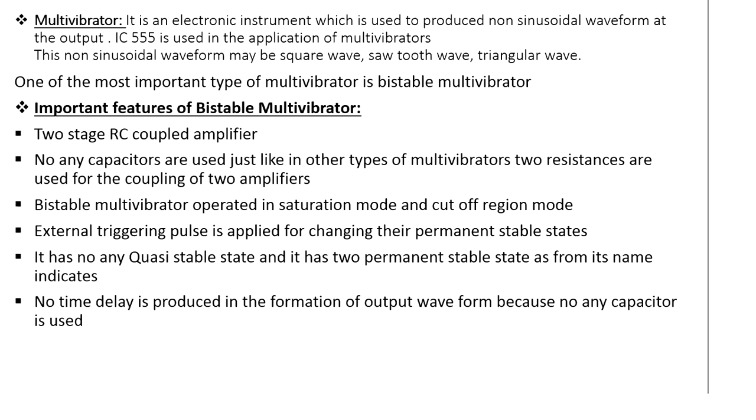When capacitances are applied, there is a time constant present during the charging and discharging of the capacitances. So there is a time delay in the formation of the output waveform in the case of the monostable and astable multivibrators, in which capacitances are used. This does not happen in the case of the bistable multivibrator, because we only use resistances, which don't change their states. Now let's move towards another slide.